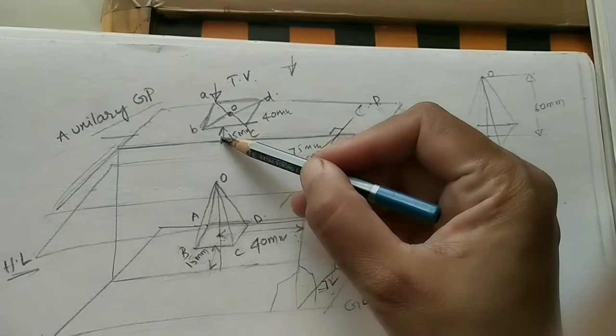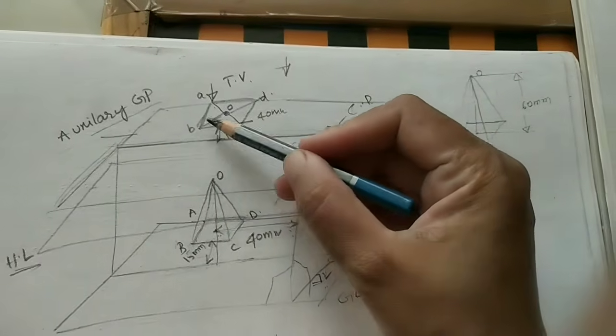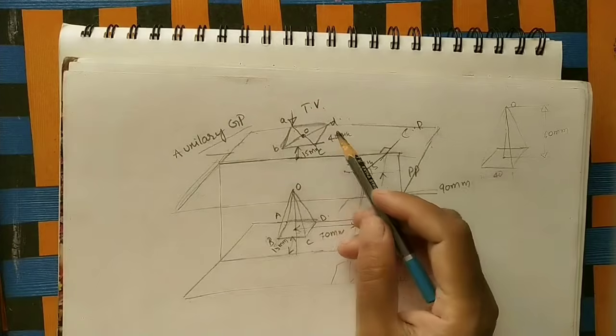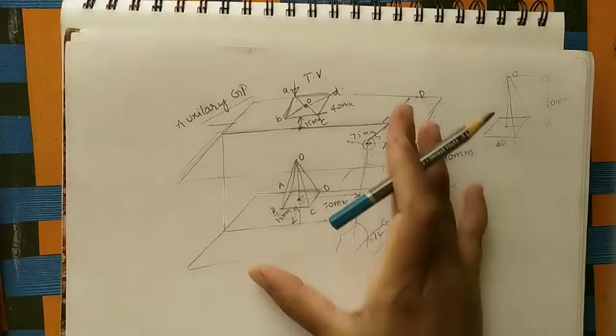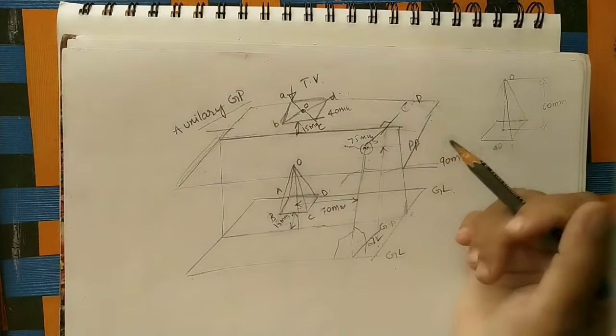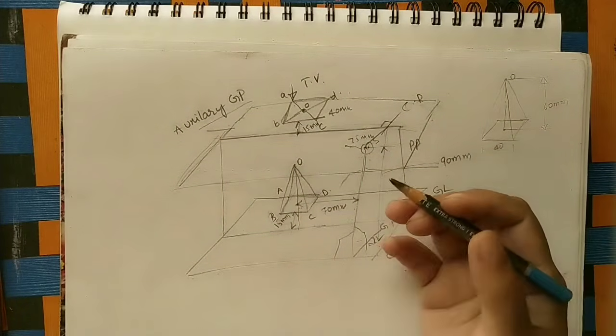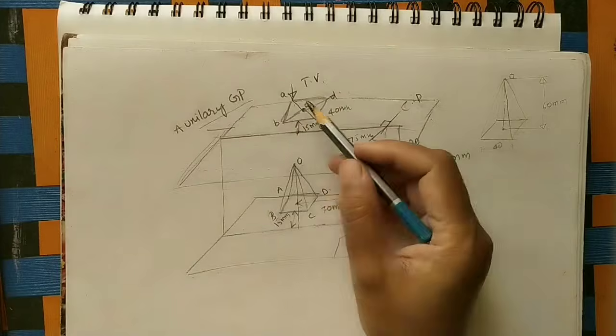Okay, and this gap we can see in the top view also. Whatever gap is there, the same gap is 15 mm. So this square here is 15 mm from PP. This is the top view we are seeing. So this is the three-dimensional arrangement, the entire setting. We need to do it in a two-dimensional diagram because on the sheet we are drawing in one plane. It is called two-dimensional. Okay, for taking this three-dimensional view into 2D.